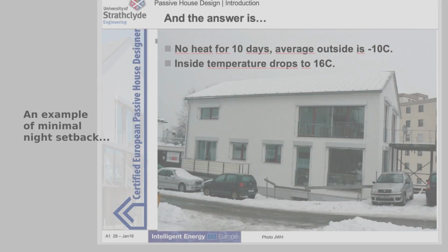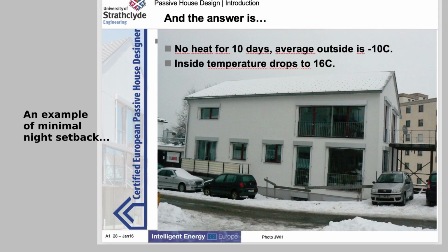With a high-performance facade, one might normally expect not much of a temperature drop overnight. Perhaps the degree for the environmental system to work back from. But I've often measured a 4 or 5 degree temperature drop overnight in a building with the same kind of insulation levels as that in Passive House, but which are only code compliant to a blower door test.